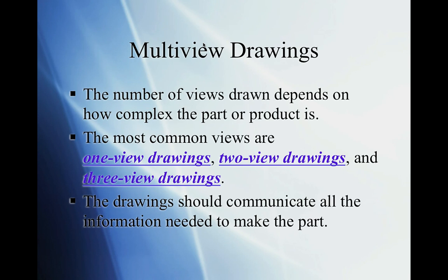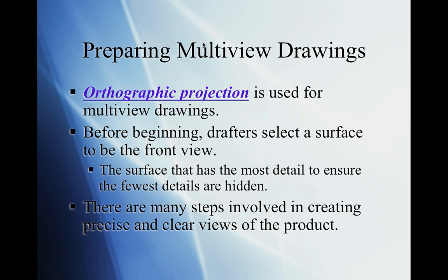But most common is 3 view drawings, but on those 3 views, you should have every dimension or all the information you need to complete that part. Okay, we use what we call orthographic projection. Again, we project up over that 45-degree angle I've showed you guys in class.